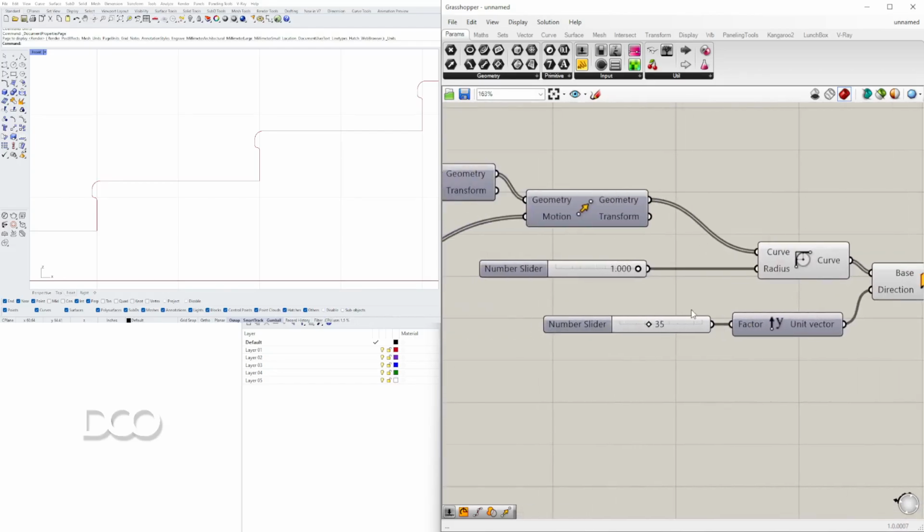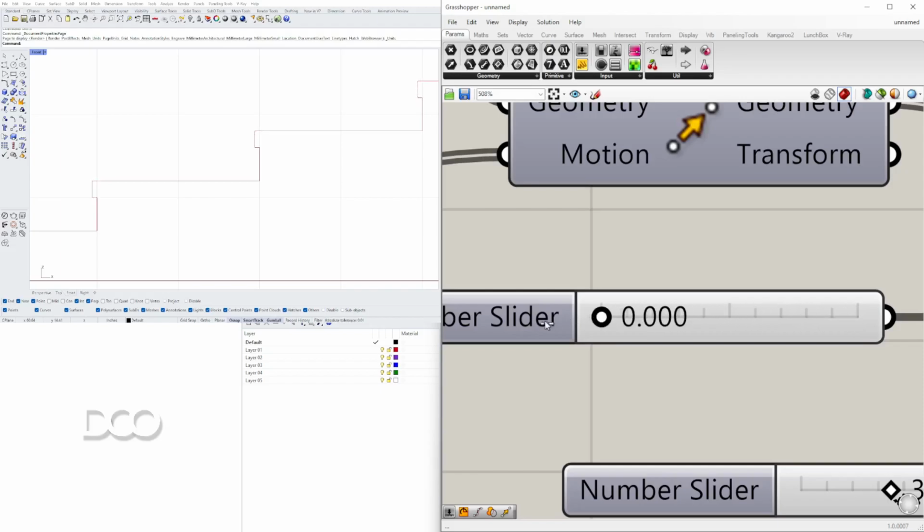Oh shoot, I guess this is the extrusion. Some of the things that Grasshopper already does by default is if you are to round this off, it'll do them all the same. But as you can see here, you're going to have the center of the split between these 2 lines. There's going to be a line segment. The length of that divided by 2 is going to be the maximum radius that you can have for this and this. And if you're going to go for this one, well, is going to be the distance between half of that and anything left over for the length of this segment, you can turn that into a radius.